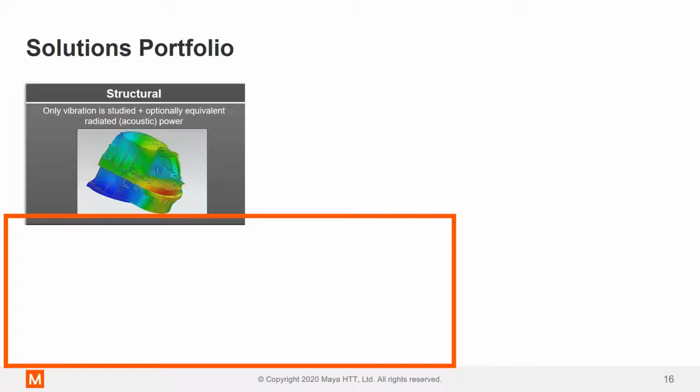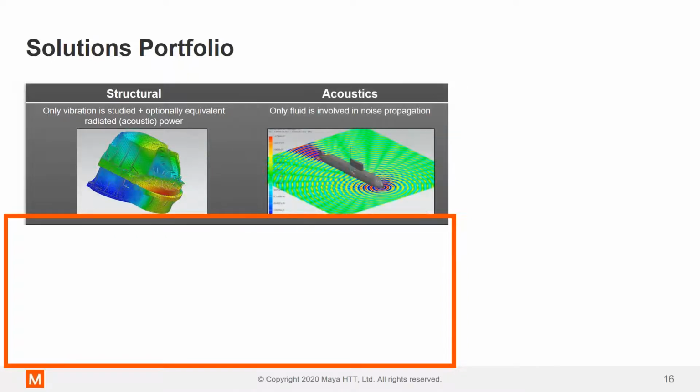Now, evidently, the next type of problem would be a pure acoustics problem, which is also supported within the Simcenter portfolio. Here you can run this acoustics problem. It could be interior or exterior, could be a FEM or a BEM method to solve the acoustic response. And within this package, to simulate such physics, it's important to consider that there is zero mean flow as an approximation.